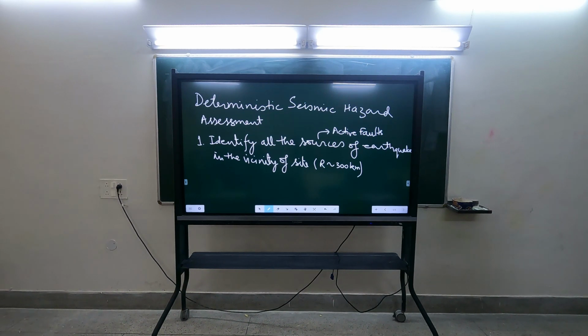Okay, so one way of looking at it is the previous record of earthquake. From previous record of earthquake, what do you know? What do you get? A ground motion. So from there, how you can identify a fault? Okay, then what we can do? From the epicenter, how will I know the source? Sir, above the epicenter, we can directly reach, some team of survey can reach and therefore they can identify. So you can plot the epicenters on a map, and wherever there is an active fault, you will get a cluster of epicenters.